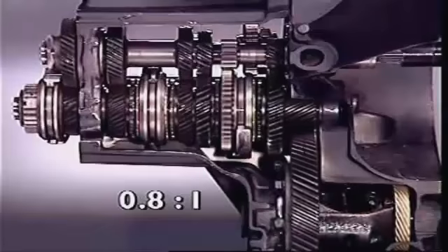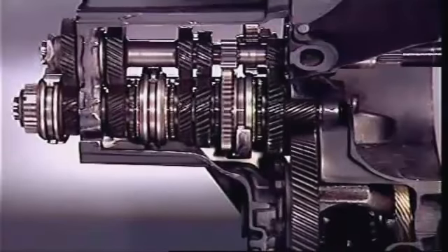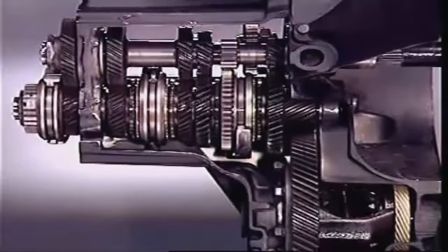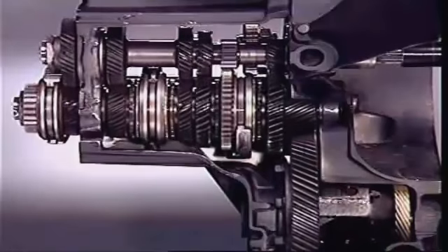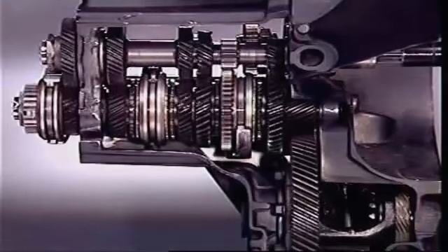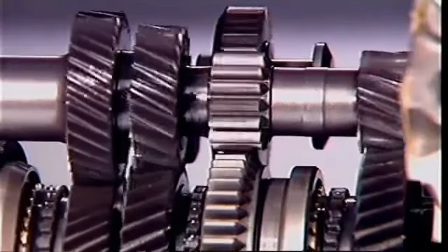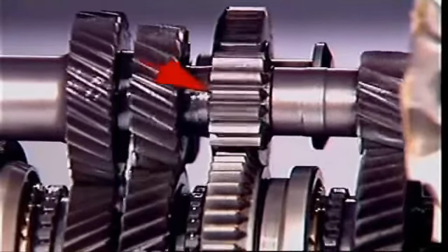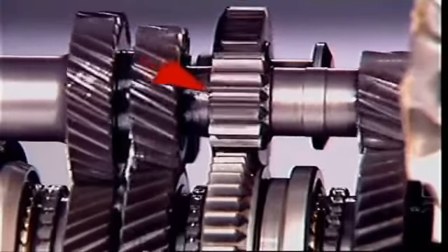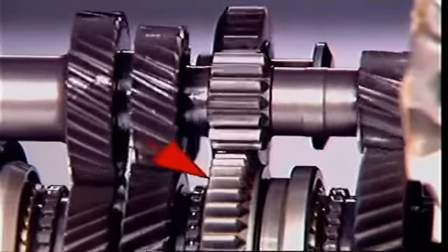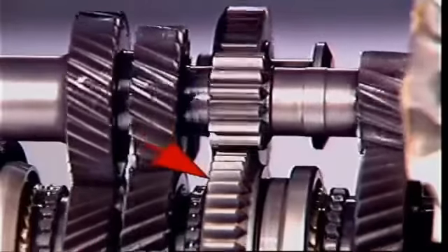This is often an overdrive ratio, with the driving gear larger than the driven gear, making the driven gear rotate at a higher speed. For reverse, the reverse idler moves to mesh with a reverse gear on the primary shaft and the matching gear teeth on the outside of the first and second gear engagement sleeve.